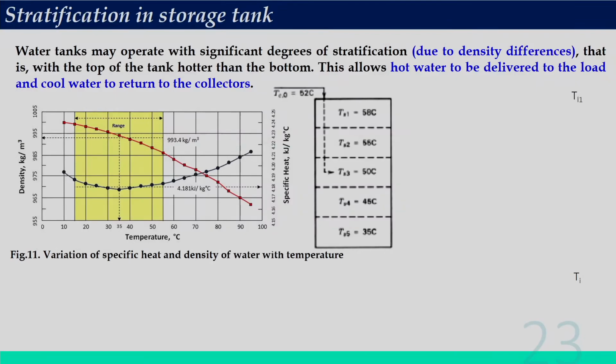Okay. So now let us consider the case for stratification in storage tank. These water tanks may operate with significant degree of stratification due to the density difference, that is, with the top of the tank hotter than the bottom. This allows hot water to be delivered to the load and cool water to return to the collector.